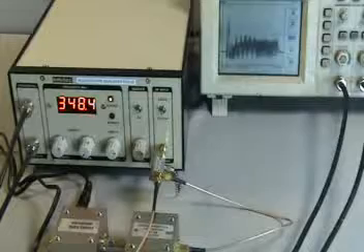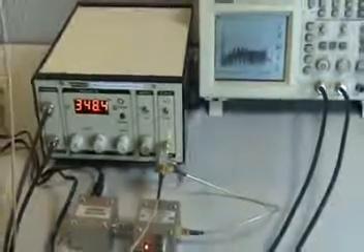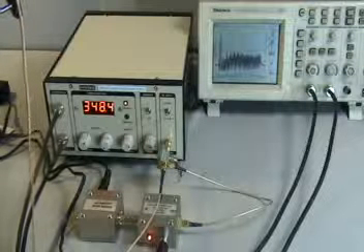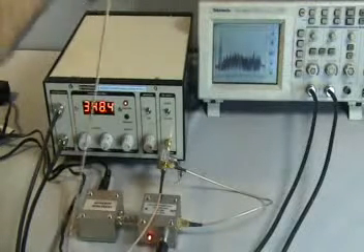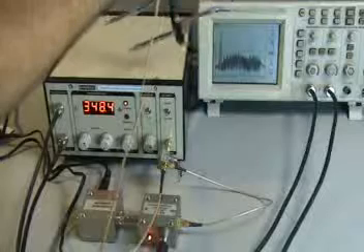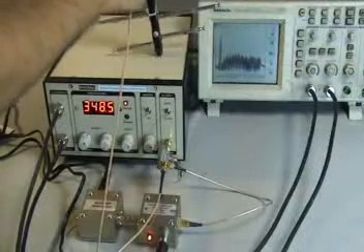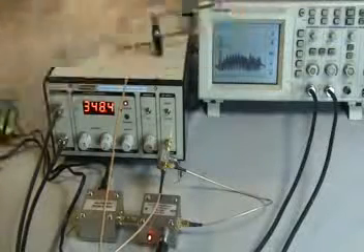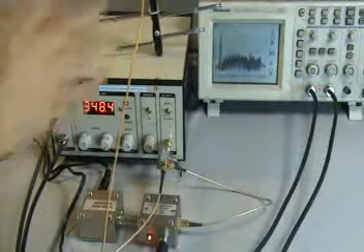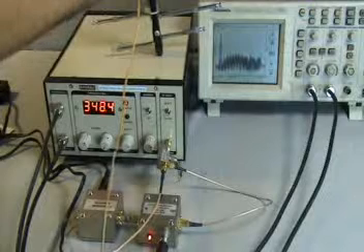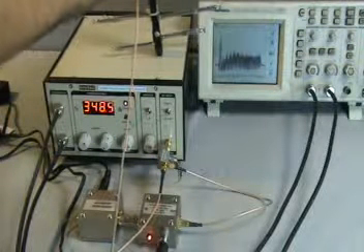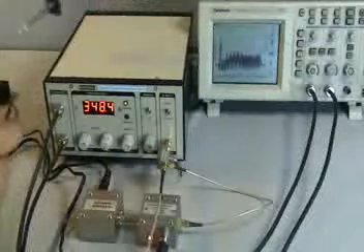Now we connect this to the input of our device, which could be, say, an antenna, and we observe that the antenna has been connected, and this will bring down the noise display slightly lower, showing that the impedance is matching to the 50 ohms impedance.